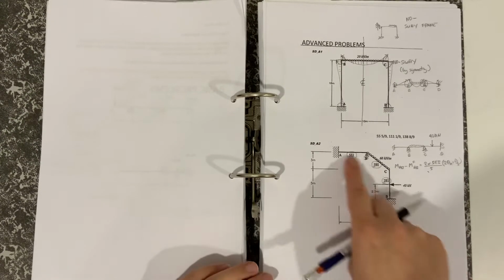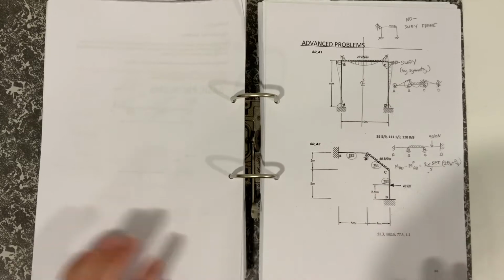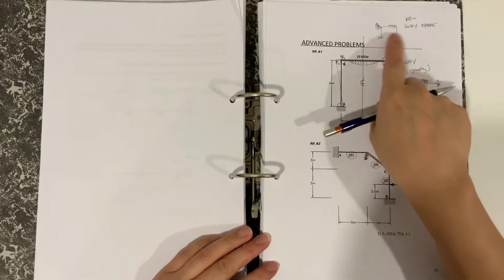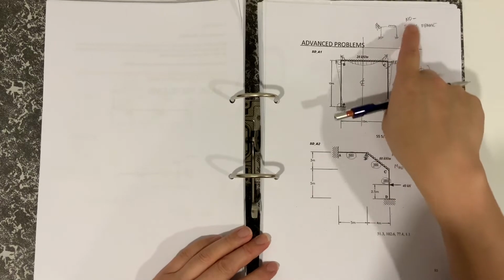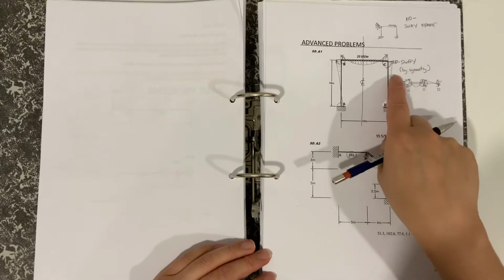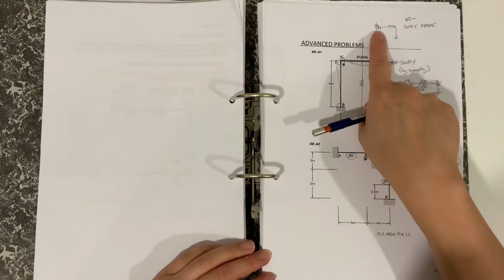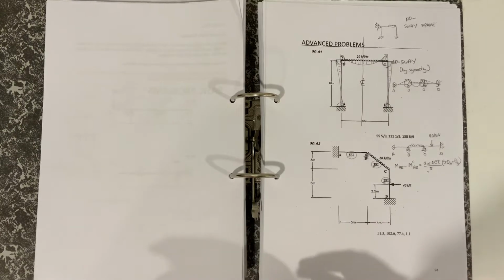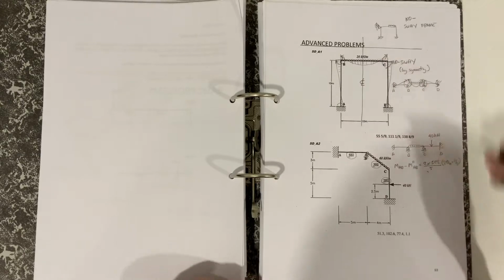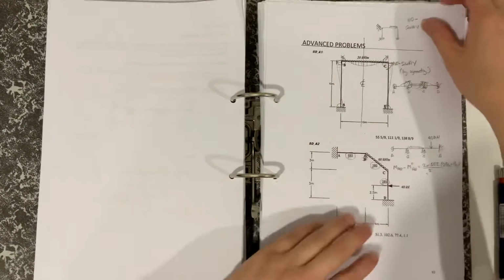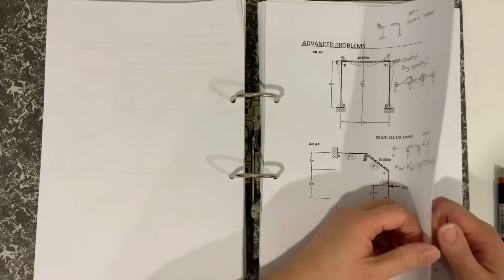and just make sure that you can do these under examination conditions, and just remember the problem of the sway frame, or the no sway frame, and of course any sway frame can be turned into no sway just by sticking a prop on that would prevent sway, just by pinning that point. So that's the end of the slope deflection part of the course.